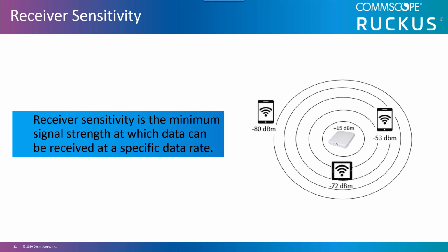Remember that dBm is an absolute measurement of power. RF sensitivity thresholds indicate the power limit of received power required to support operations. The stronger the RSSI value, the faster the communications can be. Different applications have different minimum requirements to operate and to be most efficient.